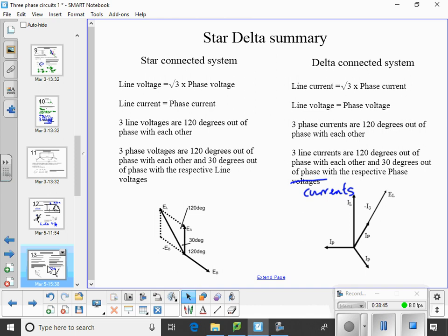The main thing about delta connected systems is they really need the load to be as balanced as possible, because otherwise you're going to get delta currents going around the delta. So a motor is generally pretty close to being balanced, whereas if you were to connect different people's houses onto a delta connected system, you're going to get an imbalance in load when people are turning things off and on. All right? So the neutral helps to handle that.